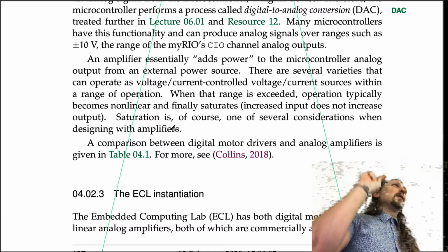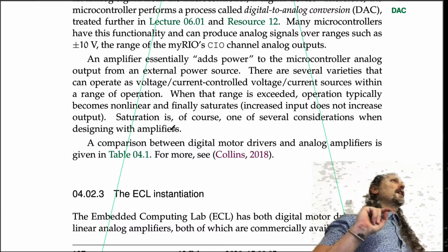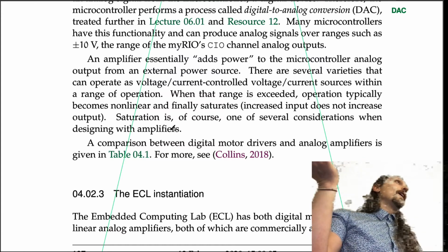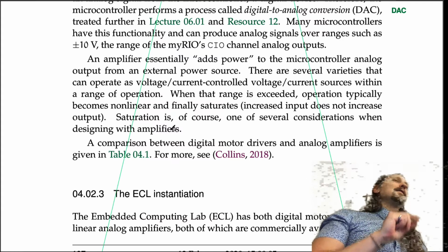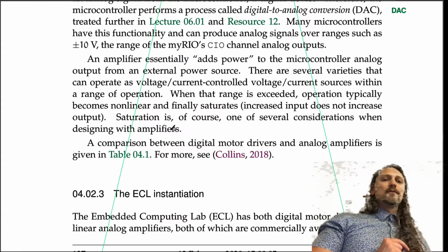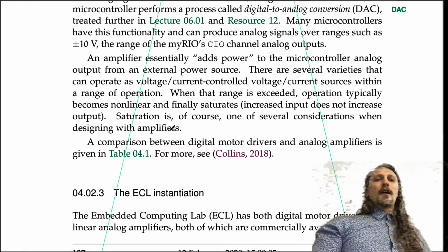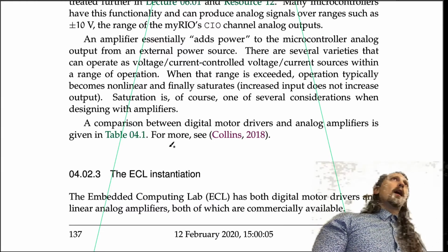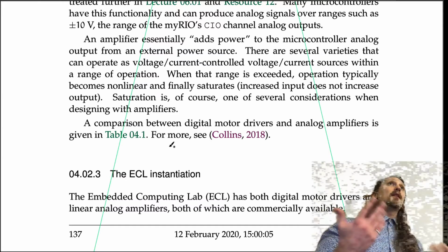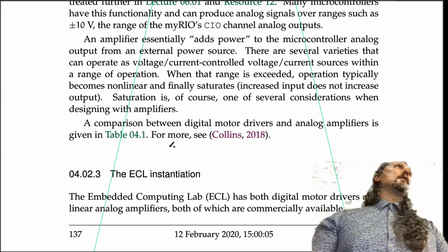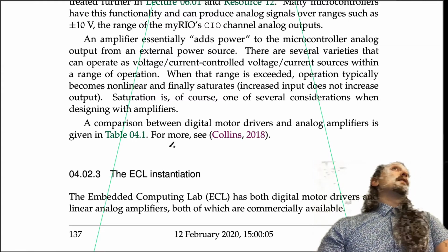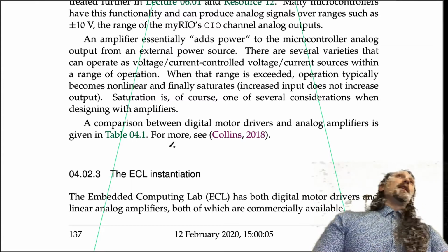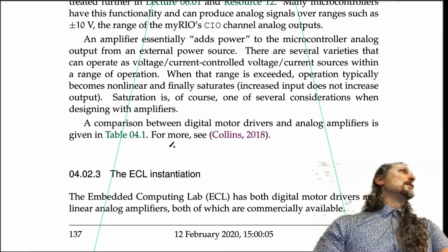But once you're pretty close to those saturation values, you put in delta X and you don't get out delta Y. You get out something much smaller. Your ability to operate linearly can be important, especially because we tend to model amplifier dynamics as linear, and if they're not operating linearly, what we expect them to do is not what they'll do.